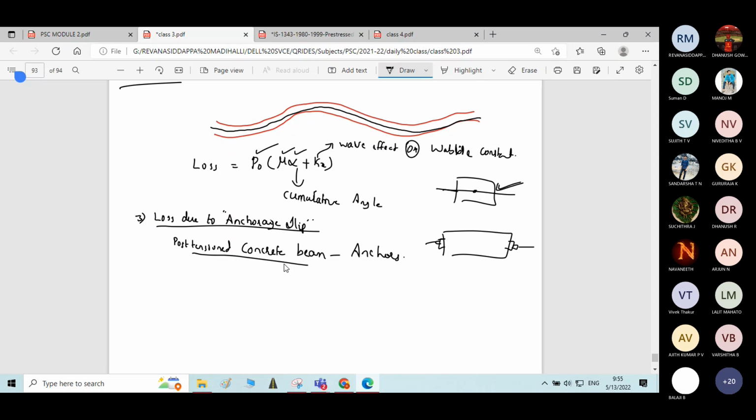In most of the post-tensioning systems, when the tendon force is transferred from the jack to the anchoring ends, the friction wedges slip over a small distance, when the pre-stressing force is transferred to these anchorages.